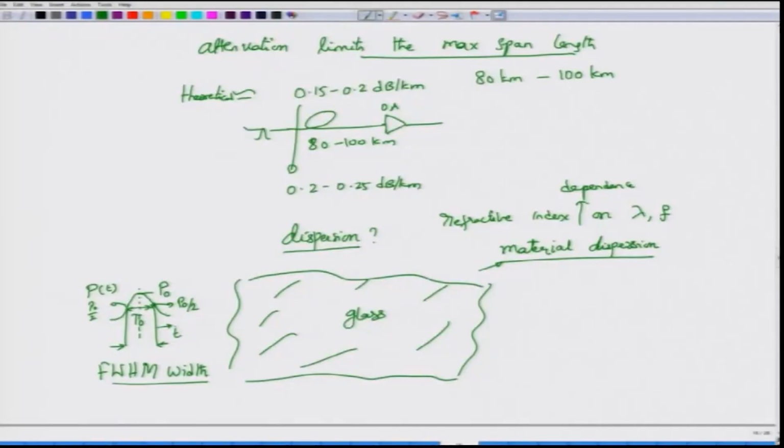And since, when you launch a pulse in time, the corresponding frequency domain picture would again be some sort of a pulse, let me use a red color to indicate that I am considering pulses in the frequency domain. And how do I go from the time domain to the frequency domain? I have to take the Fourier transform. We will have to say more about that shortly. So, when I am given the time domain pulse, I take the Fourier transform, and once I have taken the Fourier transform, I have gone from the time domain to the frequency domain.